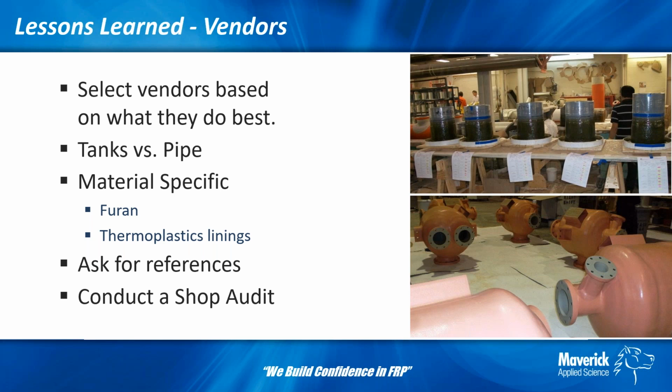And every thermoplastic has a different behavior. They have different hardnesses. They have different ranges that they have to be welded, and the ranges can vary quite widely. And the way they weld is much different as well. It's just like the difference between welding carbon steel and welding Hastelloy or titanium or something else. It takes a different skill set and a certain level of experience with every material, and the manufacturers need to be qualified on that same basis for thermoplastic linings as well.